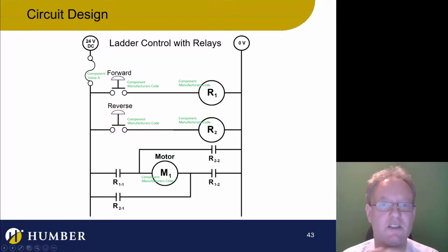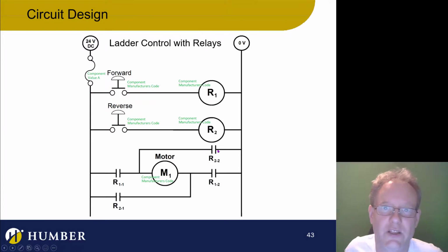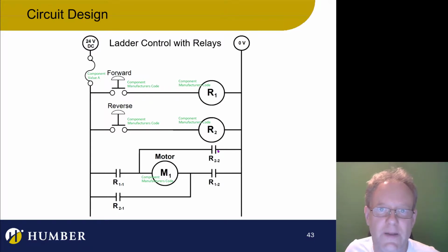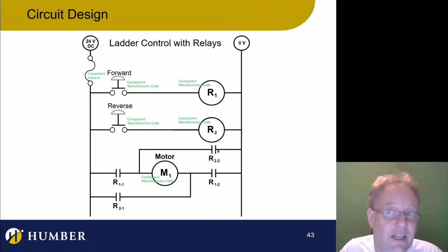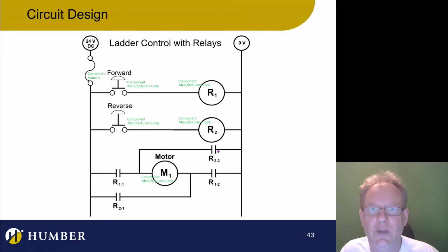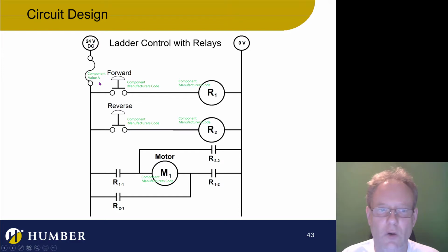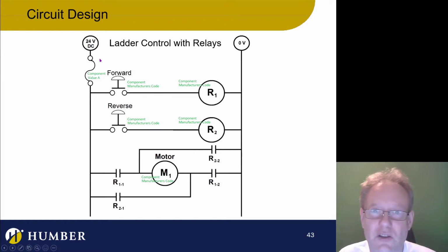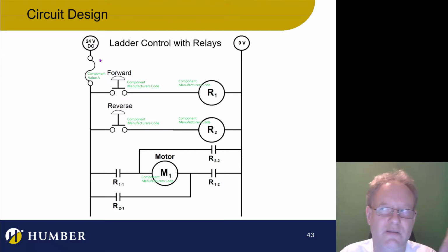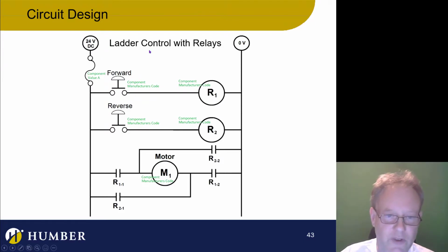And this is our ladder logic. Now, if you see here, I've put a fuse in here. And it's completely acceptable behavior to add things into ladder logic like this. So always put your fuse in when you're actually building a circuit. If you've designed a circuit and you've calculated a fuse, stick it in here. Maybe in your first step of design you don't put the fuse in, maybe stage 2 or stage 3, at some point you're going to say, okay, I better choose a fuse. This is pretty simple circuit control, so you can calculate the fuse pretty much in the first run. Okay, so put your fuse in.